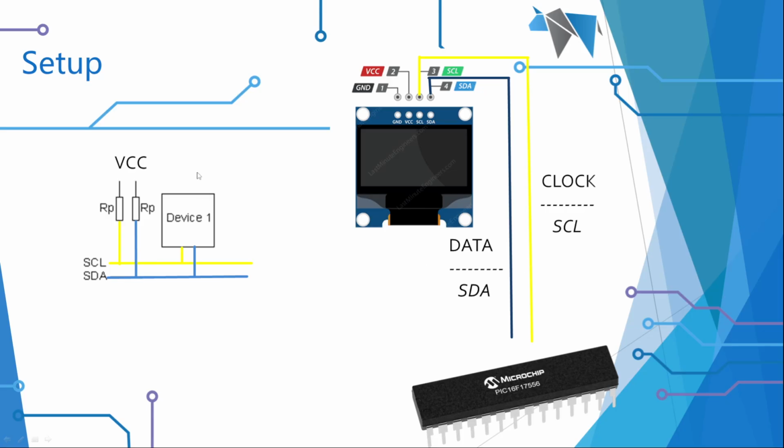So I have got some pull-up resistors on the VCC. That's important. These are my pull-up resistors, one here and one here. Typically I use 4.7k or 2.2k. And I've got those lines pulled high. And then I've got a yellow cable connected and a blue cable connected to my GLCD device. I always use those colors because it's just so clear when you have multiple I2C devices. You can go, that's the clock line, that's the data line. One is blue, one is yellow. There's no confusion.